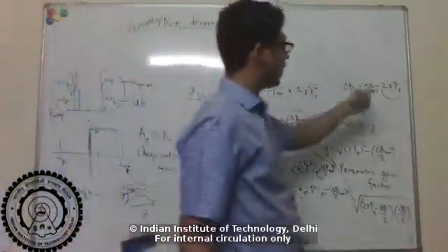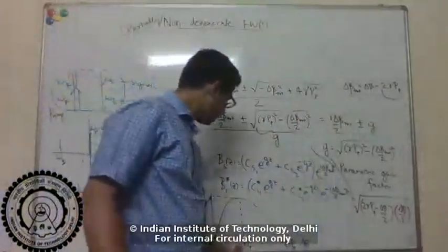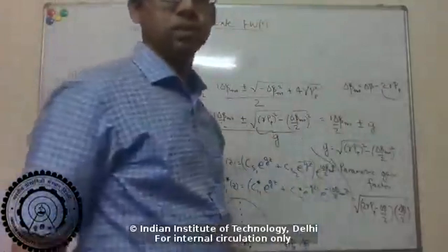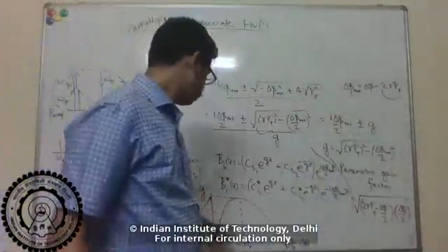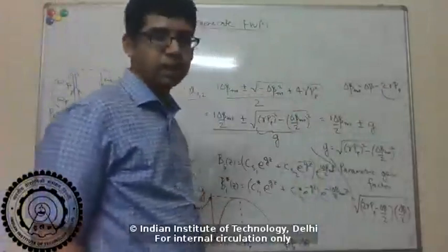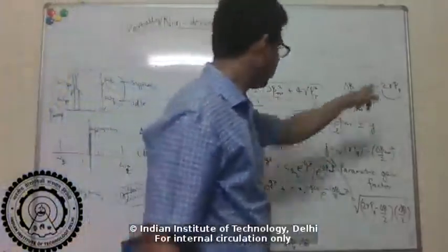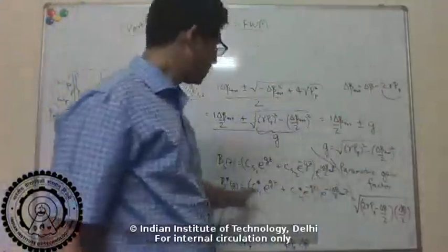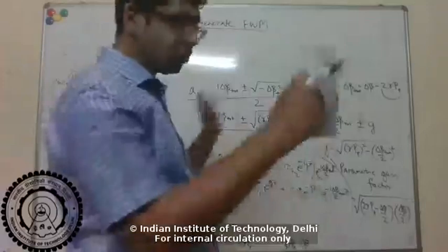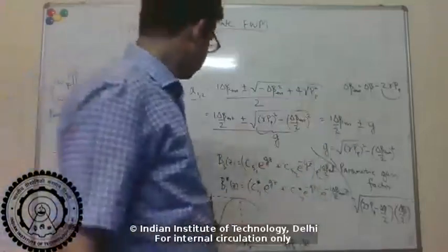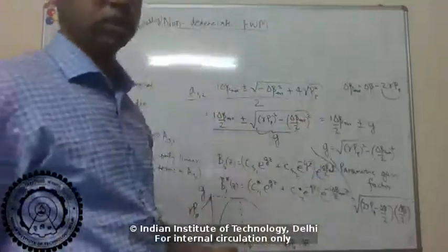So you have to compensate for that nonlinear phase shift, which you get by having this finite delta beta. Okay. So what is happening is basically if your actual delta beta is 0, if you make your phase mismatch 0, your process is inefficient because of this nonlinear phase shift which takes it away from the phase matching, right? So to get total phase matching including the nonlinear phase, we actually want a slight phase mismatch in the original case.